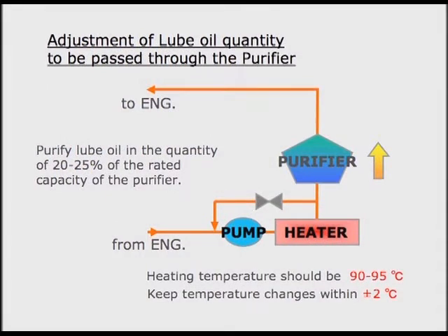Conduct the cleaning treatment with the feeding oil quantity covering 20 to 25% of the rating capacity of the purifier. Set the heating temperature at 90 to 95 degrees centigrade. Keep the temperature variation within plus or minus 2 degrees.